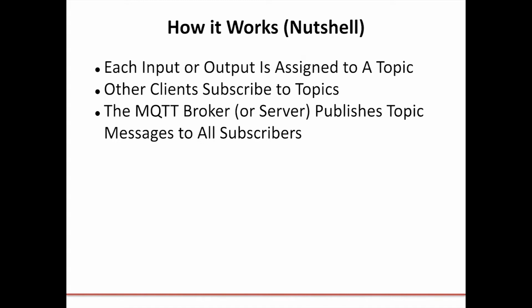So how it works in a nutshell is that MQTT is a messaging protocol. It manages messages between MQTT clients and MQTT brokers or servers. Originally, they were called brokers, but now the term servers has become pretty ubiquitous, and you see them both used pretty frequently. So in a data acquisition application, both data acquisition modules and their controllers are considered MQTT clients. They both send and receive messages through the broker.